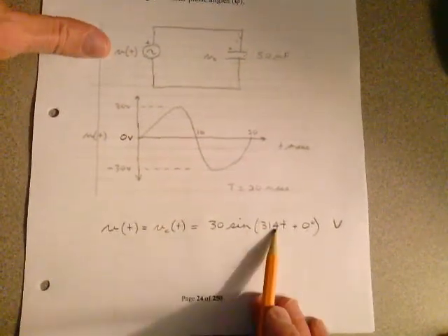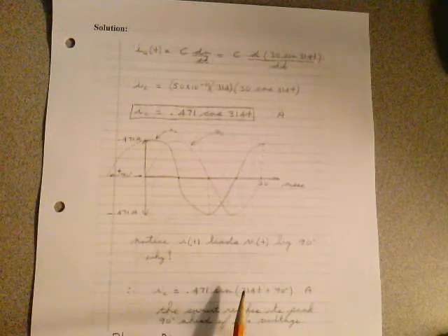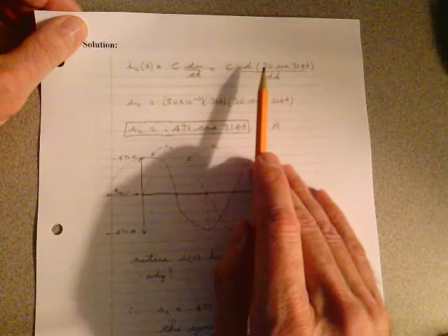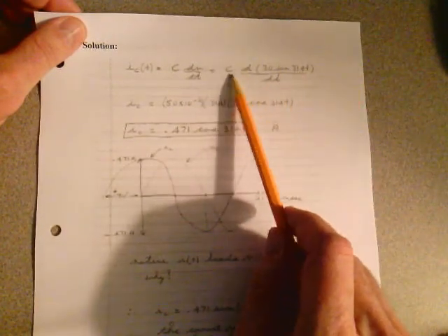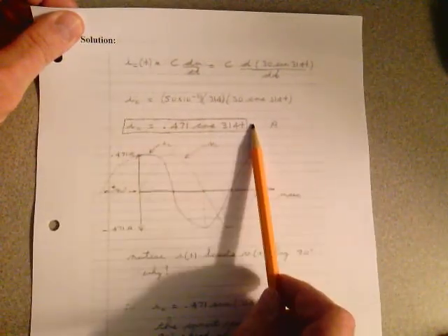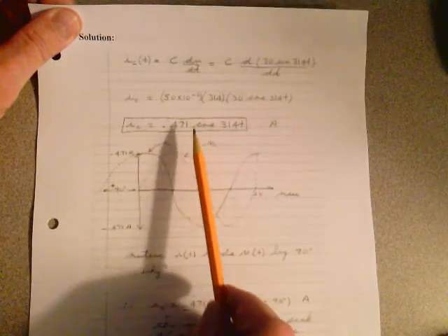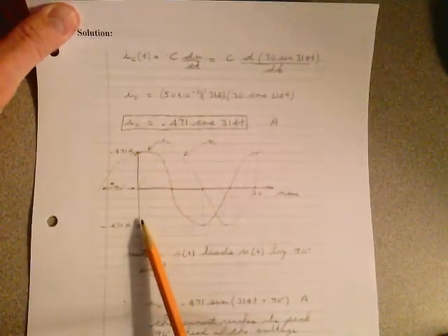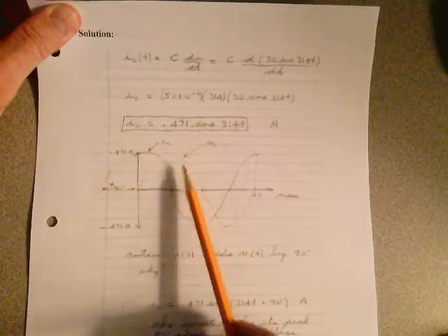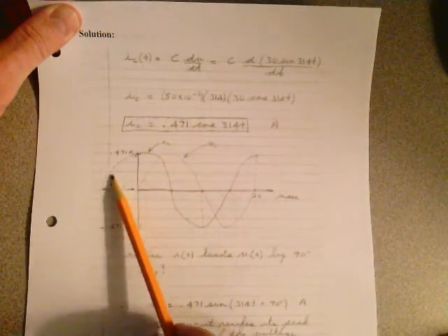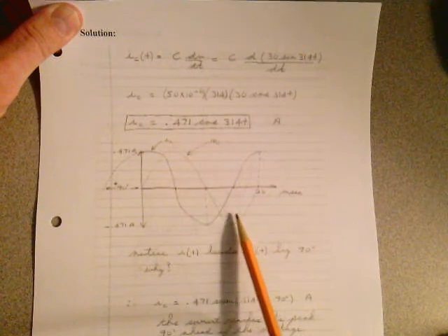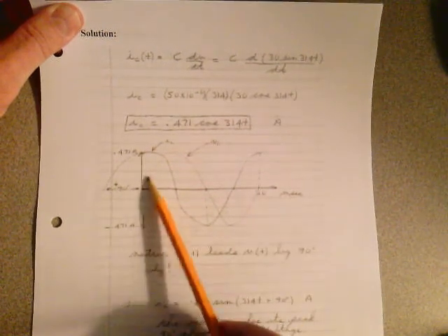So once you get this, you're going to know from a previous lecture that the current in the circuit is equal to C dv/dt. You already memorized that. Take capacitance times the derivative of that voltage, and here you have the current in the circuit. I drew a picture of that current waveform down there. There are two different scales here, don't forget. I'm showing current, and then this other one is voltage, and the voltage scale is going to be different from the current scale. So keep that in mind here. But here I have my current waveform, which is a cosine. Here I have my voltage waveform, which is a sine wave.